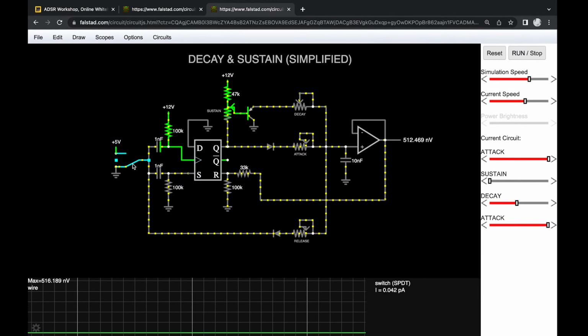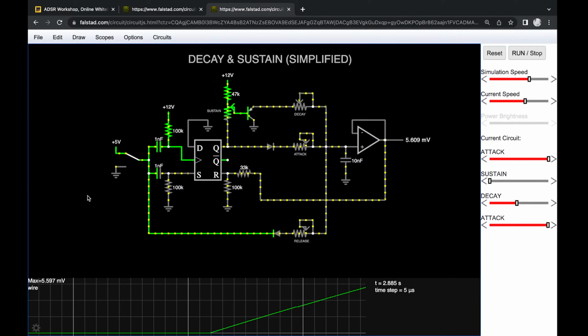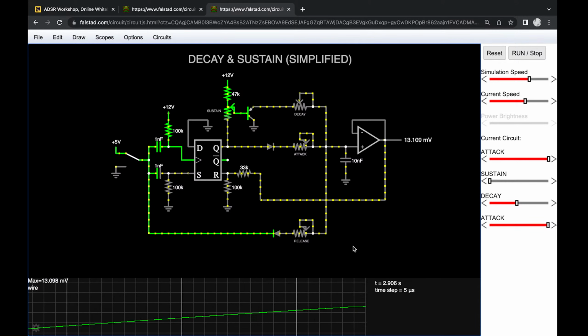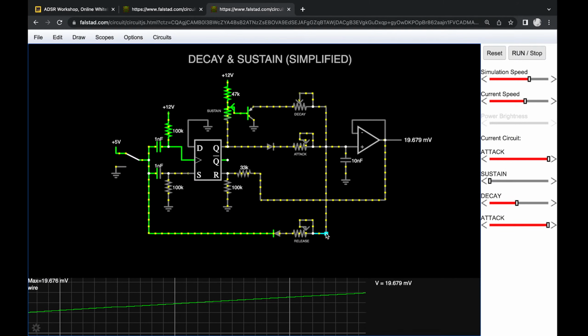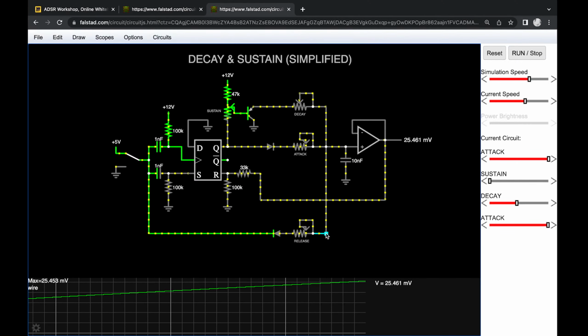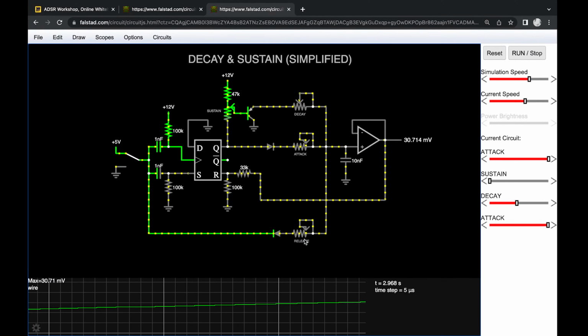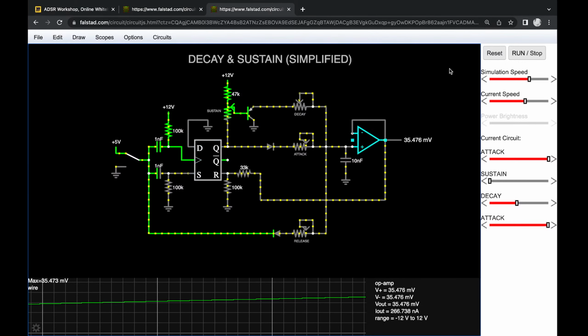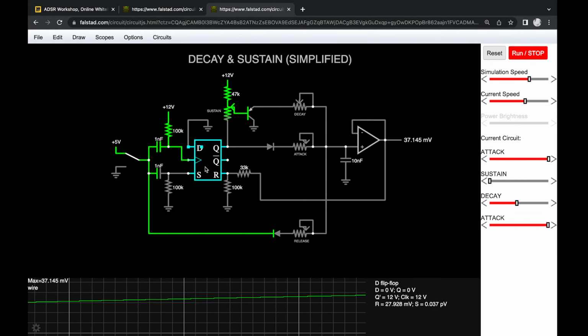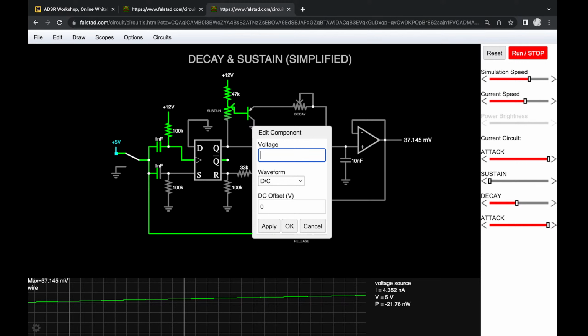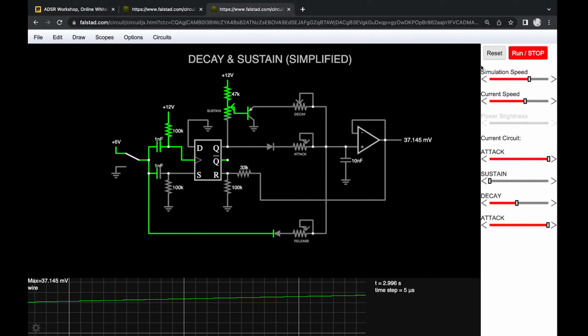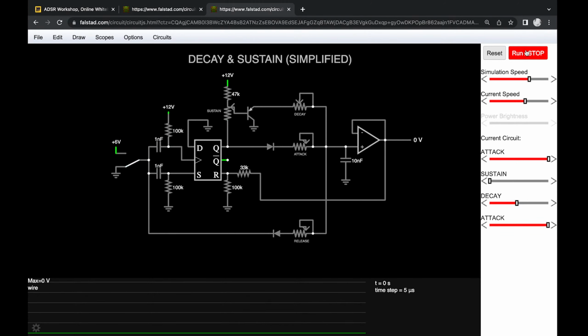then we would have the following problem. So we engage this, and as soon as... Oh, is it even worse than I thought? Why is it not charging at all? Oh, right. So this won't work in the first place, simply because the flip-flop will not register this as a logic 1. I just explained that the CMOS will only register this as a logic 1 if this is 6 volts or higher. So you would have to bring this up to 6 to actually see any effect here.